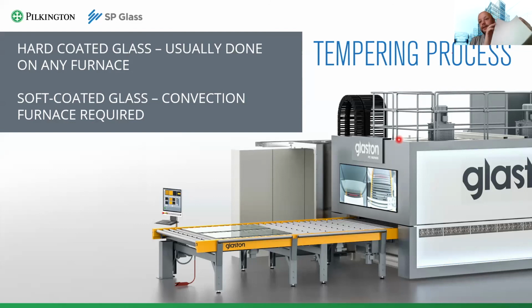Why is that? Because the coating of soft-coated glass cannot be put on the rollers of the furnace. So if you have a facade which looks like this from the inside, bent outwards of the building, you don't have any problems. Soft coating is positioned on the surface, everything's fine.